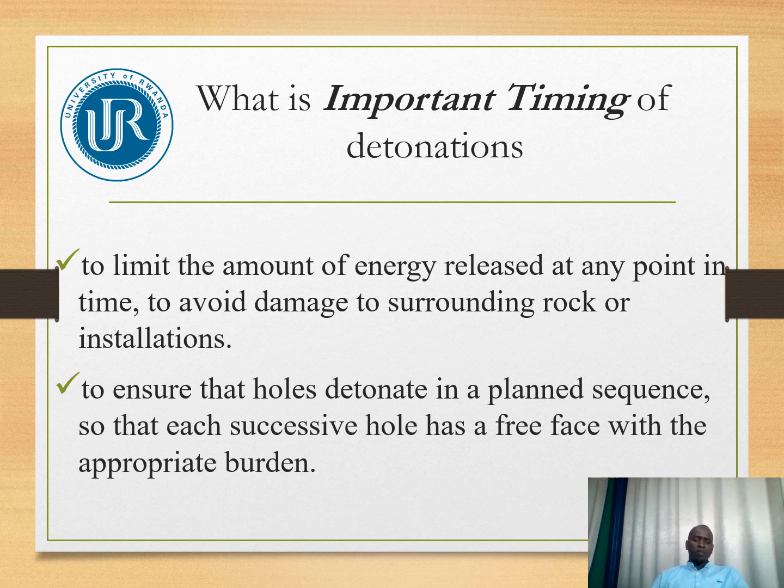So what is the importance of timing of detonation? This is there to limit the amount of energy released at any point in time, or to avoid damage to surrounding rock or installations. This also is there to ensure that the holes detonate in the planned sequence, so that each successive hole has a free face with the appropriate burden.